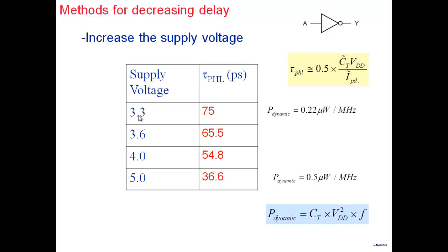The other thing, of course, is when a manufacturer is saying the optimum supply voltage is 3.3, and you run it at a higher voltage here, there is of course a safe limit within which you can run. But in general, if you drive it at higher, as you can see, higher power dissipation, there may be issues of reliability and other things also. You will end up dissipating more heat and there may be problems.